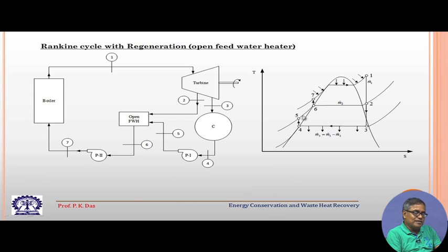At this condition the liquid from point 5 to this point, the steam condensate has to be heated, and this is generally, in our earlier example whatever we have seen, done in the economizer. So, in the economizer, the flue gas is used to heat condensate from the pump outlet condition to the inlet condition to the evaporator or boiler drum.